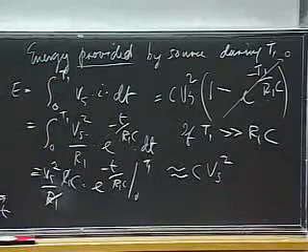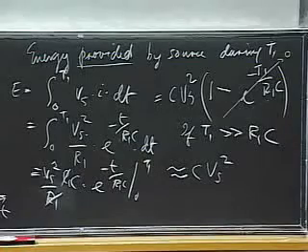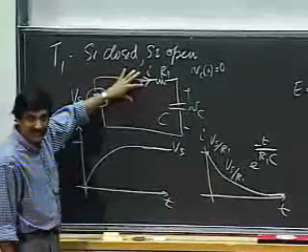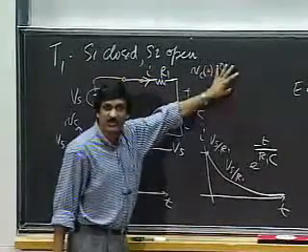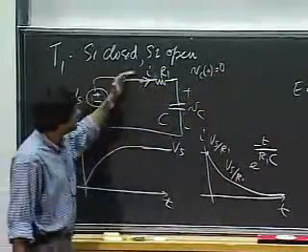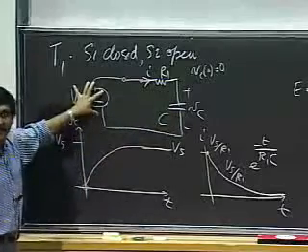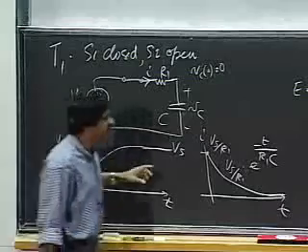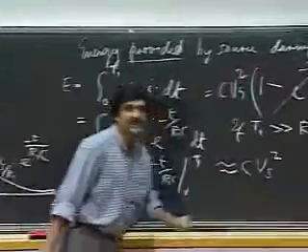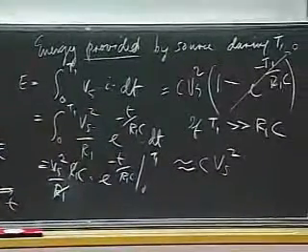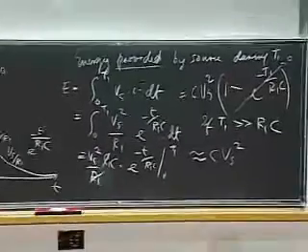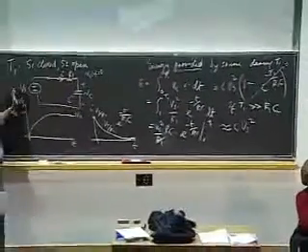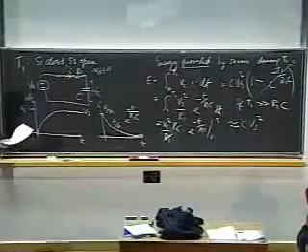What do we have here? What we have here is that if I let the switch stay closed for a long time and S2 be open, then the voltage source is going to supply some amount of energy. That energy will equal C Vs squared. So the voltage across the capacitor will be Vs, and all that energy would have been supplied by this guy.